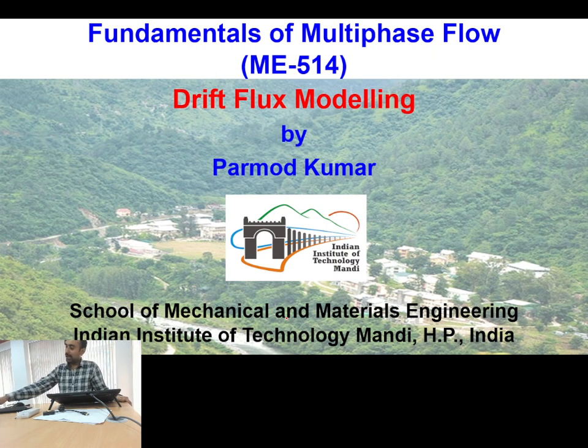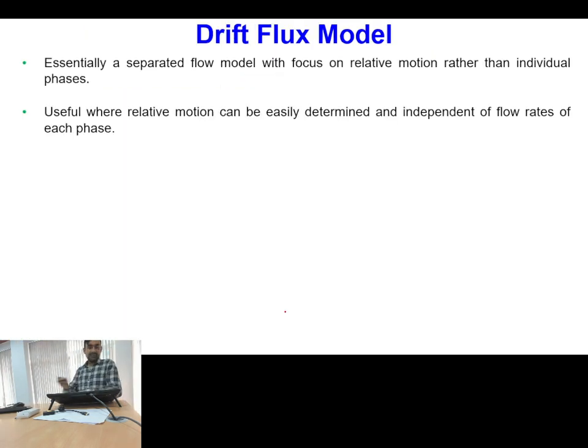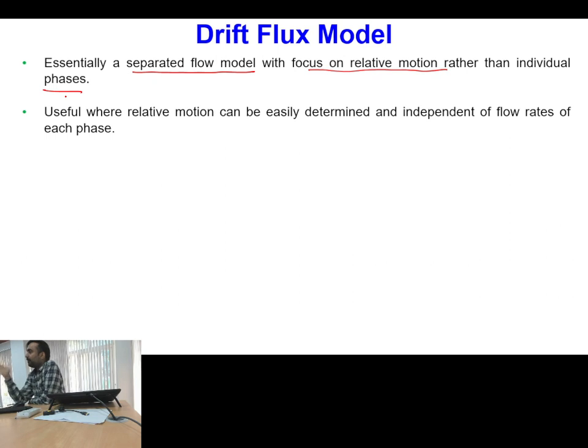So ultimately, the drift flux model is nothing but a separated flow model only, but here the specific focus is on the relative motion rather than the individual phases. A true separated flow model is one in which we solve separate continuity, momentum and energy equations for individual phases, and then we consider the interaction between the two. So that is a true separated flow model.